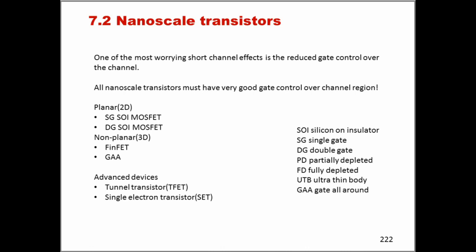So since we've started realizing that there are short channel effects in a standard planar MOSFET transistor, as I'm thinking now to the many diagrams we've seen up until now, where our transistor is the standard planar device with source and drain and gate stack on top, people have been trying to come up with ideas that could help in giving back control to the gate